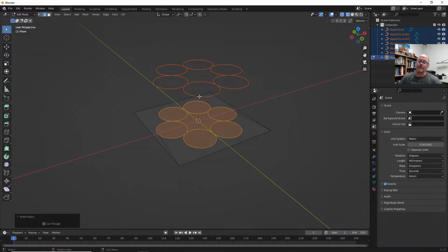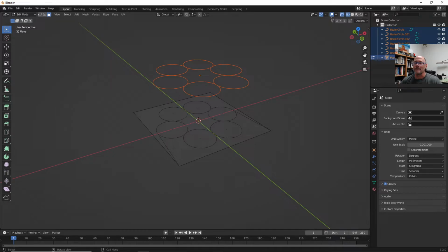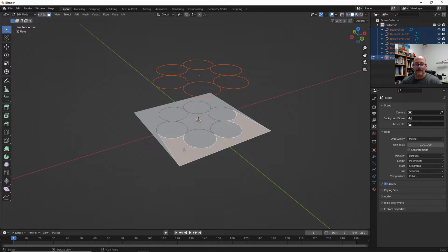And because I increased the resolution of those circles, I should get a nice fine curvature around for my fidget spinner. So we should be able to select the faces. I can hit 3 on the keyboard, not the pad, and that switches to my face mode, if you will. Let's go to shaded view here. So I can select and shift click the different faces, and I'm going to select these 3 as well.